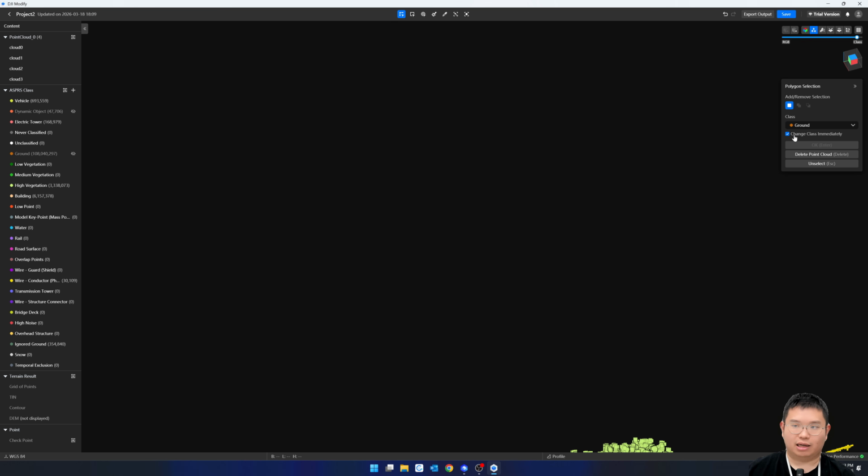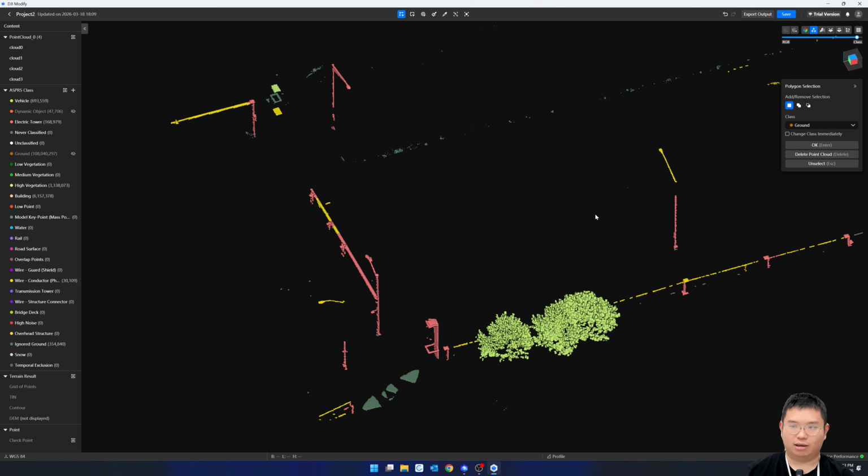And currently it's set to class ground, meaning any point you just selected would automatically get classified to the ground class, which wasn't right. So we're going to uncheck this, okay?